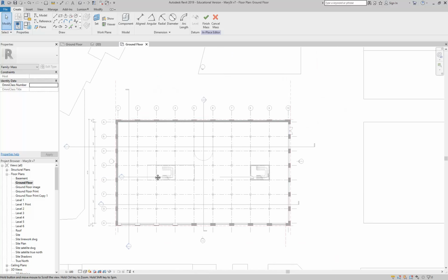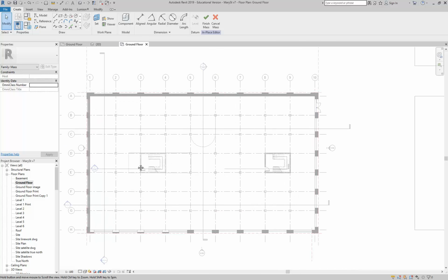So the idea when you're doing massing for conceptual modelling is that you want at least a different element or a different component, or you'll see in a minute, form is the other term, for each of your spaces. There are different approaches then to the way you group it, moving on to things like fire stairs and other primary elements, but I'll start off just with some different forms.